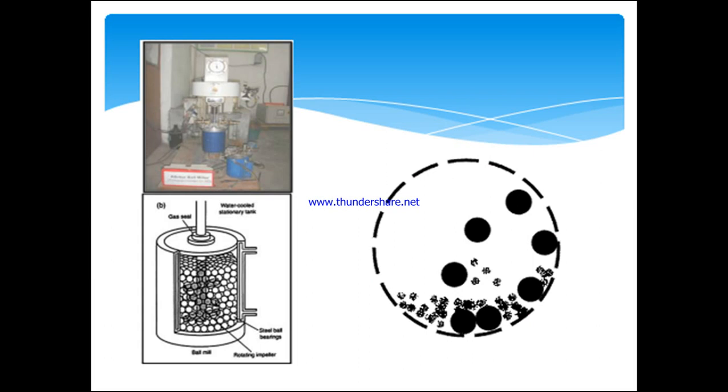So when we are having a similar size of the balls, that is the tungsten carbide or it may be the hardened steel, whichever it may be, if we are having the similar sizes, then the uniformity of the nanoparticle, that is in terms of homogeneous materials, we are going to get that homogeneous nanoparticle materials being generated here. Otherwise the material will become heterogeneous here when the sizes of the balls go on varying.